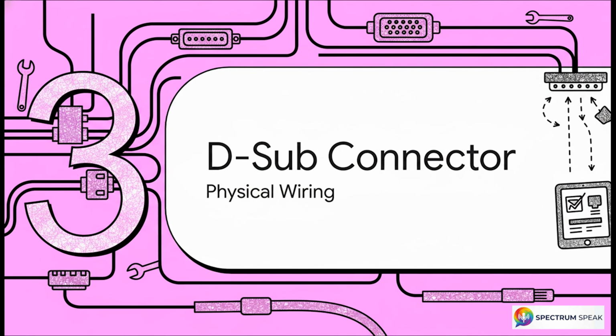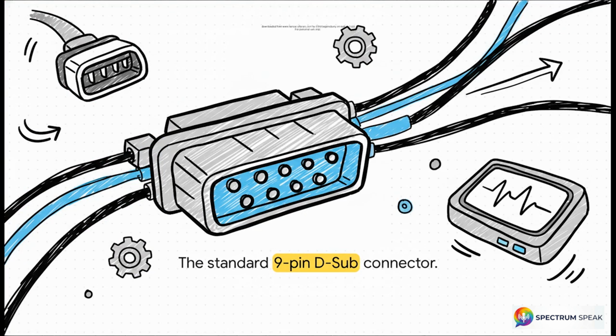All right, Section 3, wiring the D-sub connector. Okay, we've covered the internal architecture and the abstract standards. Let's move to a practical, real-world example and see exactly how we physically tap into this network. Based on heavy recommendations from the CAN in Automation User Group, often just called CiA, the industry standard way to physically interface with CAN controllers and test equipment is via a standard 9-pin D-sub connector. It's that classic D-shaped plug you've probably seen 100 times on testing hardware.